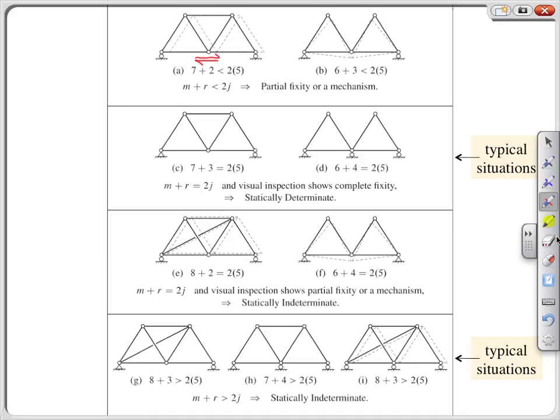The second, truss B, actually undergoes a combination of movements. Its left side can pivot about the pin, and a clockwise rotation is shown by the dashed lines. In order to be consistent with our assumption of rigid body motion, the right side must simultaneously rotate and slide to the left in a combined translation and counterclockwise motion.